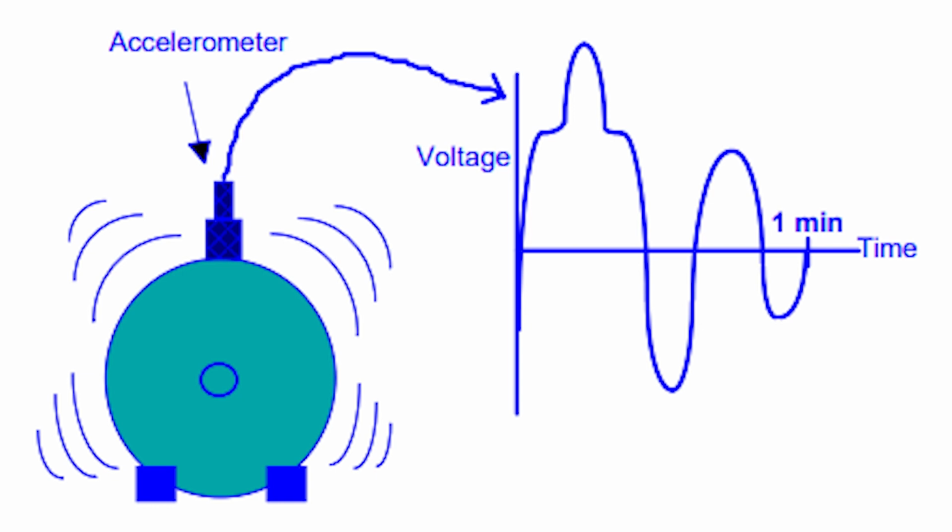The data collector records the raw data in a time waveform, which is a graph where amplitude and time are both represented. It is important to remember that vibration isn't typically the cause of a problem, but rather a symptom.